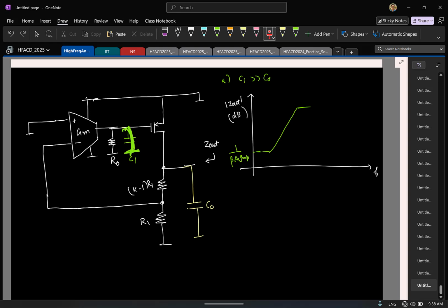And interestingly, tell me this. To find the output impedance, essentially, let us say I inject a test current. I find the voltage. That's the experiment I'm doing, right? For finding the output impedance. So in this case, I see that my capacitor C1 is shorted, but my output is not 0, right? I'm applying an input current and trying to find the output voltage, correct?